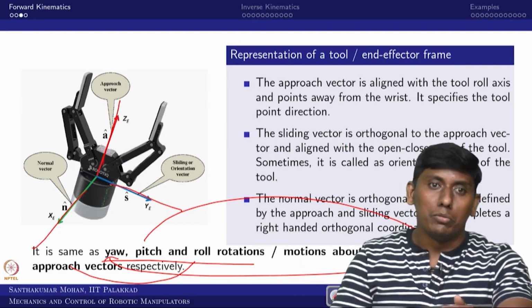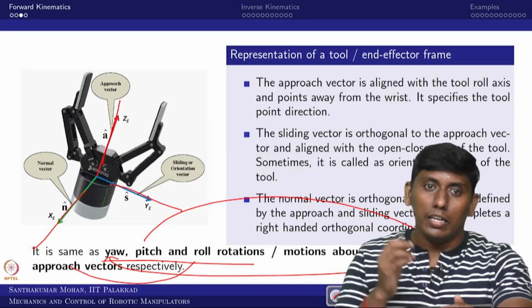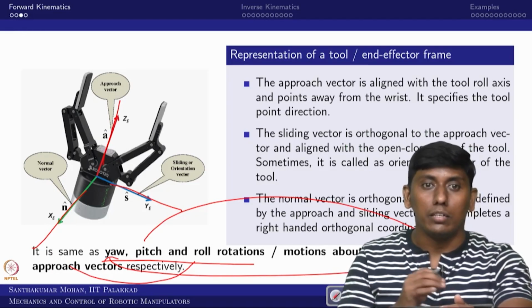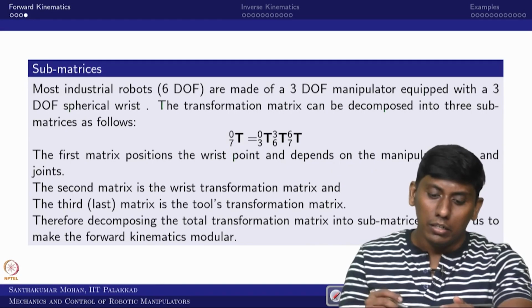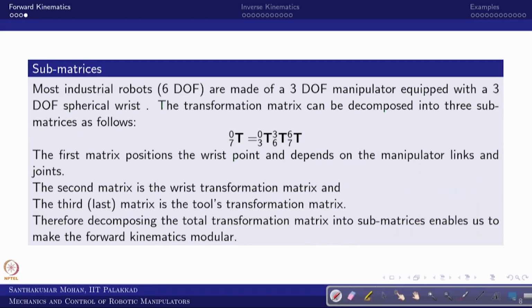So, this is actually much more convenient for the industrial manipulator community, so that standardization can be brought in. I hope now you are clear. So, based on this, if you take a 6D arm, that would be a 3D manipulator with a 3 degree of freedom spherical wrist, in the sense it can configure the translation and this configures the orientation, right.